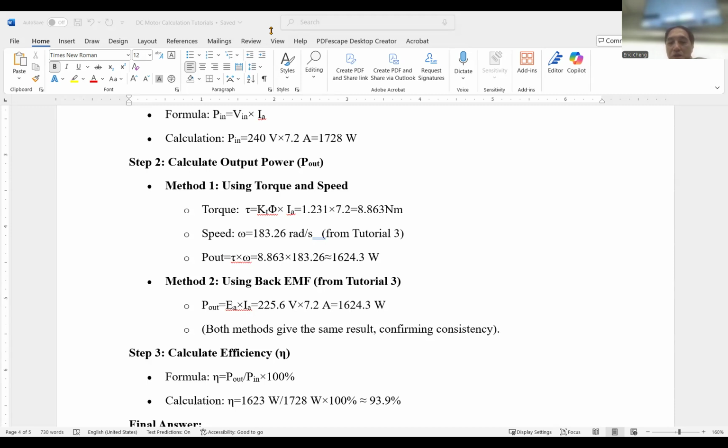So the voltage applied to the armature, again, we use the duty ratio, right? The voltage is the average voltage. 400 volt multiplied by 0.5 becomes 200 volt. That's the average voltage you can see at the armature. And for the EA, taking out the volt drop on the resistor, that gives you 192 volt. That's reasonable because we only have 200 volt applied to the motor. And once we have the back EMF, we can divide by the motor constant and get the radian per second of the motor speed. Under this operating condition, we got 96 radian per second. We change it to RPM, easier to observe.